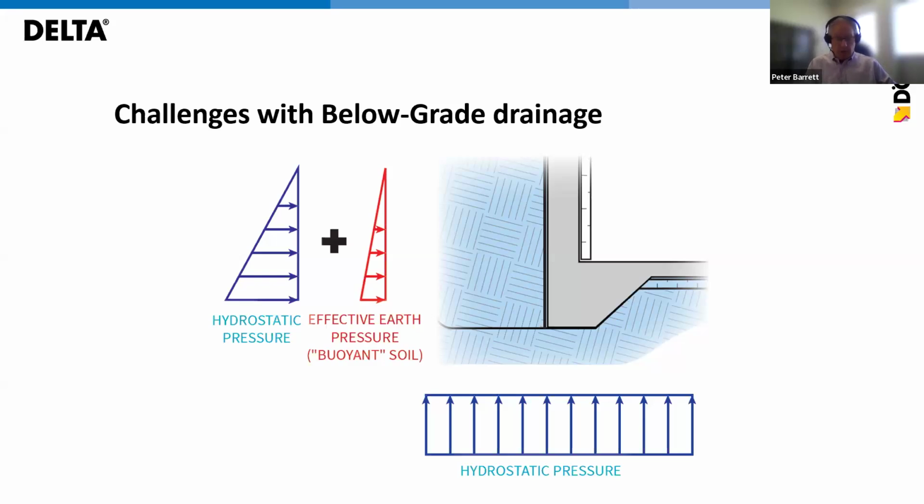As water moves through the ground, it will look for the path of least resistance. Water does that pretty much anywhere. Namely, it will move through the looser soil. It's much easier to drain through the loose soil than the compact stuff before it ultimately starts accumulating against your building's foundation. This is what we call hydrostatic pressure.